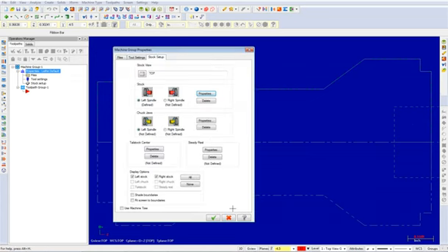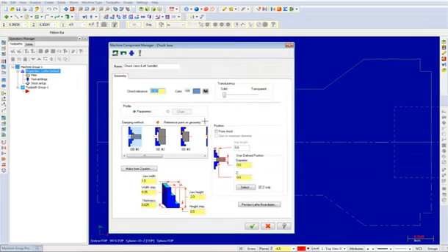Now, under Chuck Jaws, ensure left spindle is selected and pick Properties. Select the clamping method OD number 1 and enable the option under Position From Stock and Grip on Maximum Diameter. Input a grip length of 0.75. Select the OK button to exit the Chuck Jaws dialog box.